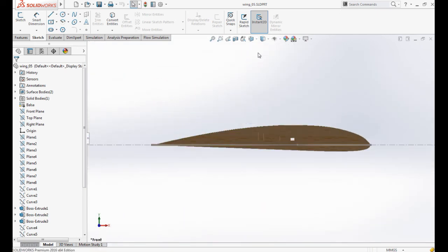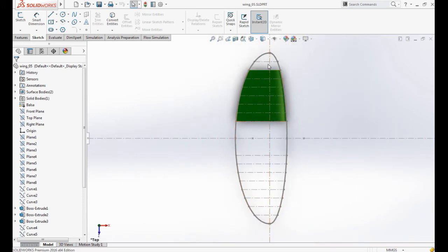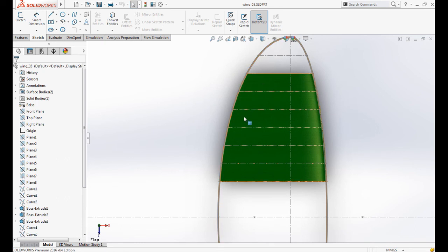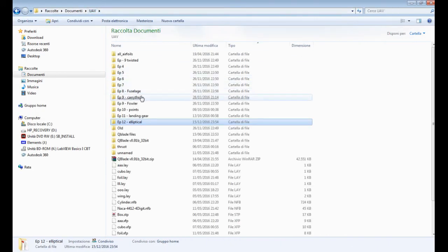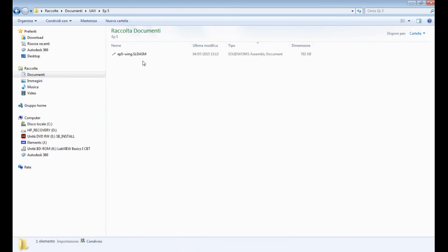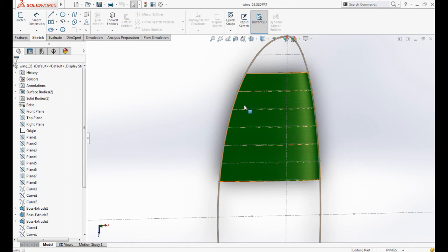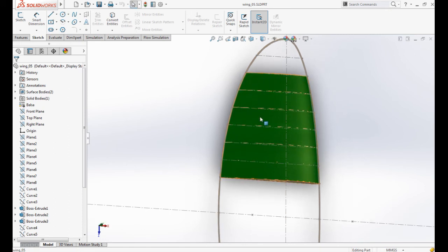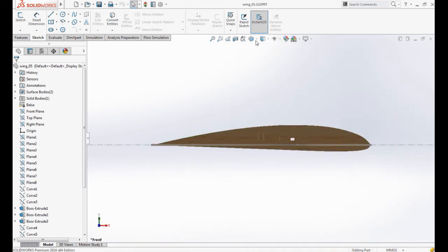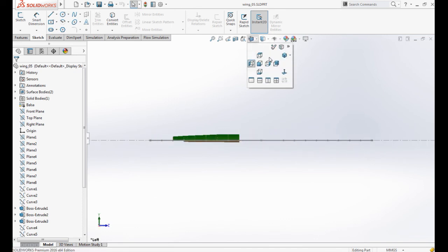In case you will need to make this elliptical wing with some flaps and some ailerons, the technique is the same I showed you in the previous episode, which I think is maybe 4 or 5. Yeah, episode 4. So you will need to shape all the aileron, all the airfoils, in order to make the room here. And also, as you can see, there is no twist here.